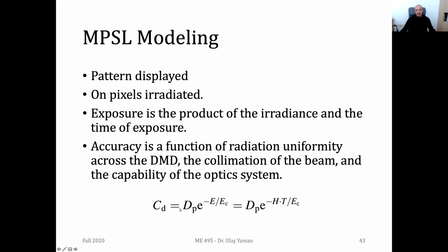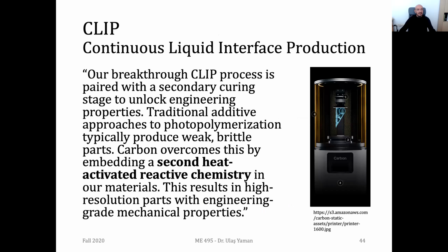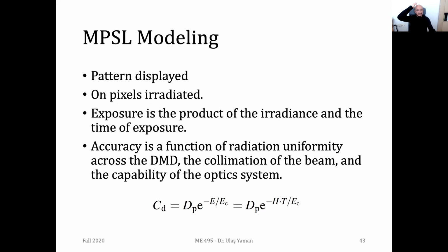And as you see, again, we have a similar relationship between the curing depth, the depth of penetration, and critical exposure values. So by, again, using such a relationship, you can adjust the curing depth and have parts fabricated with specific layer thicknesses. Any questions, guys, about fundamentals on mass projection lithography?